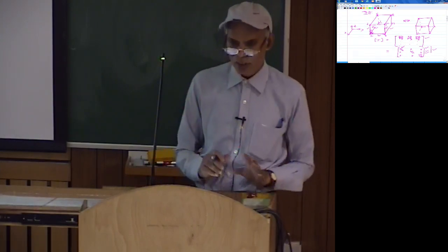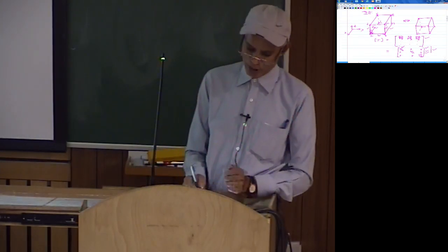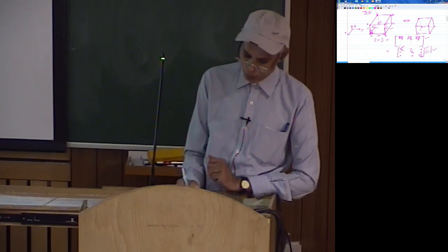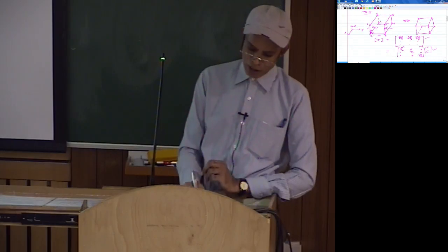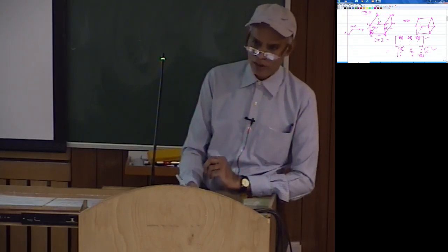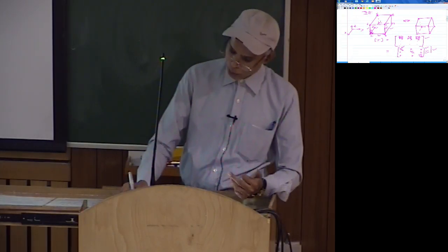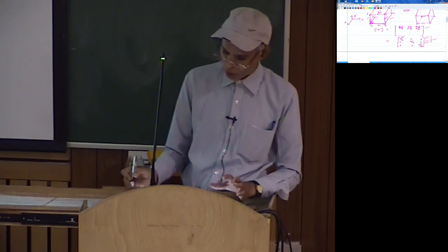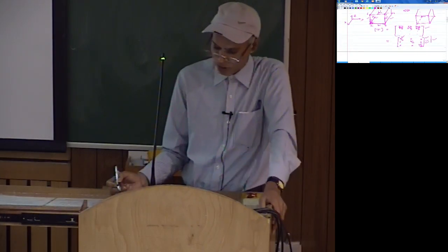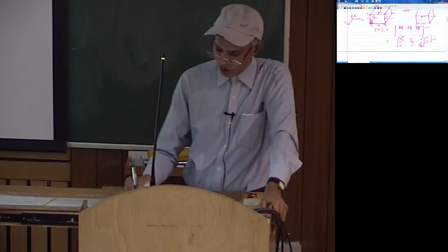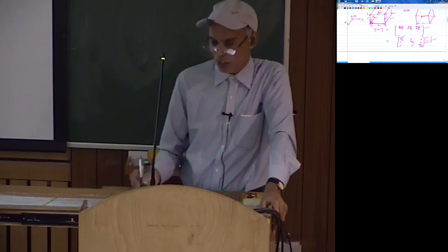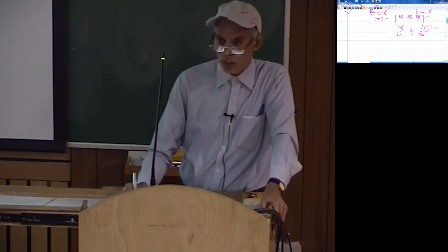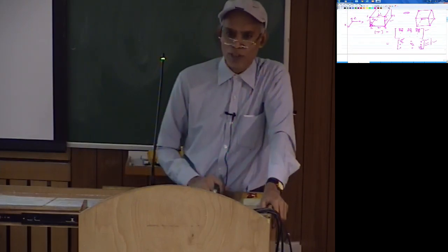So again, the criteria for the shape of the elements are similar to what we have for 2D in terms of aspect ratio and the included angles. Of course, for 2D, particularly plate bending elements, there are a few more in terms of out of plane distortion, in plane distortion, and the out of plane curvature and other things. So they also should be within certain limits. So this was another question. Is this clear? So, similar arguments.